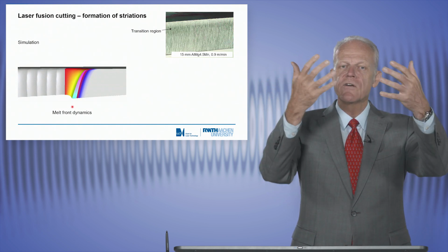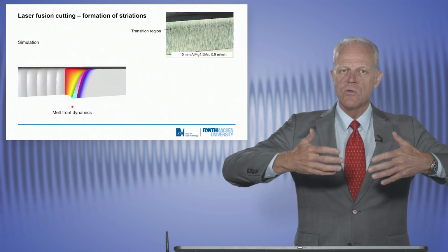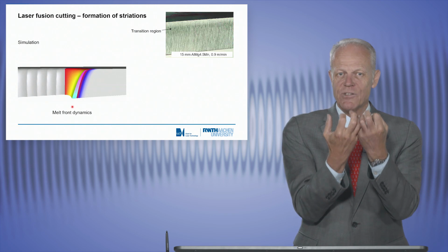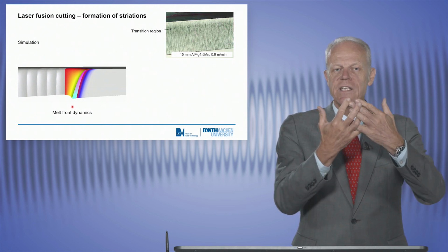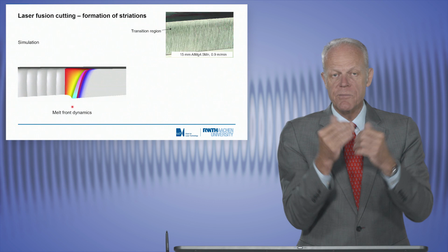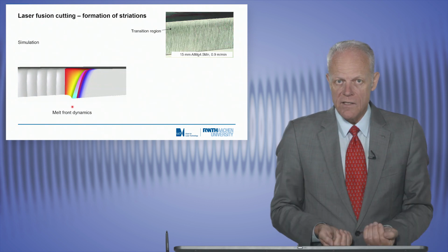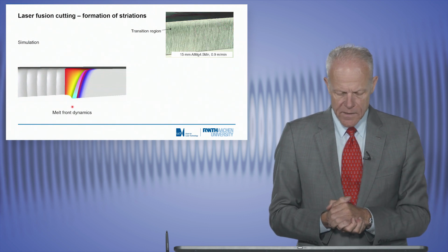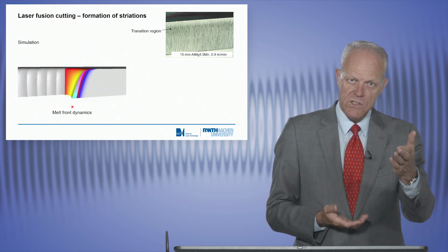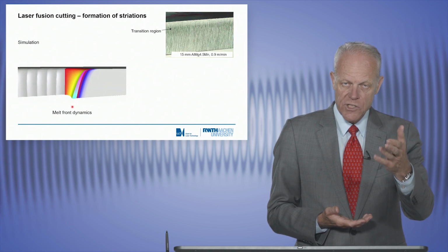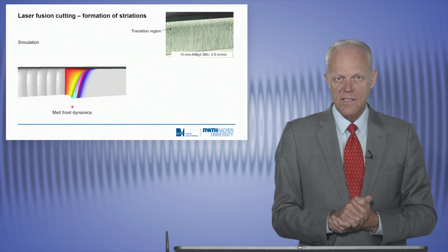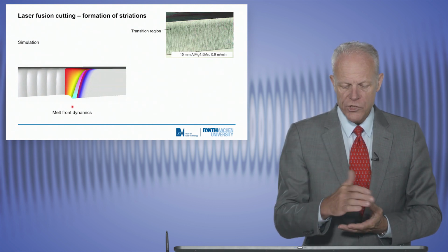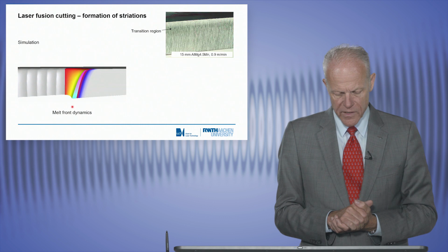But as soon as you have more drops coming to the window at lower parts of the window, you will see that then gravity in this case exceeds the surface tension of the drops and the drops will start to run down the window. So that is exactly the same process here, just that the gravity in the water analogy here in the laser cutting is the accelerating gas jet which pushes out the melt film.